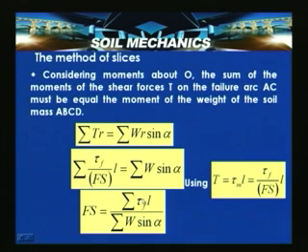Now, considering the moments of all these forces about O, the sum of the moments of the shear forces T on the failure arc AC must be equal to the moment of the weight of the soil mass ABCD. So, considering the moments about O, the sum of the moments of the shear forces T on the failure arc AC must equal the moments of the weight of the soil mass ABCD.